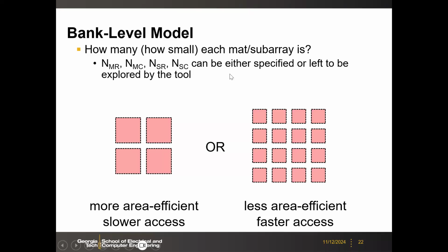So here then, the general design consideration is that given the same capacity of the total memory array, how do you partition that? Let's say each subarray becomes larger, or you design it smaller, right? So there will be a trade-off between those two cases. Even though the total number of bits are the same, you can tell, right?